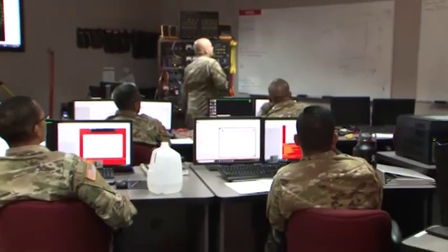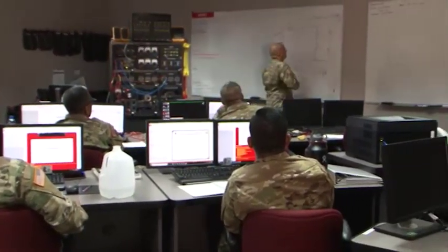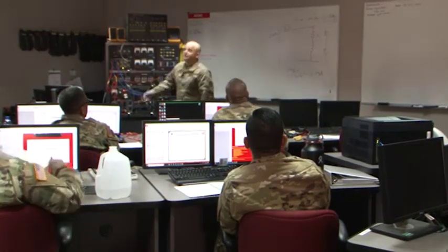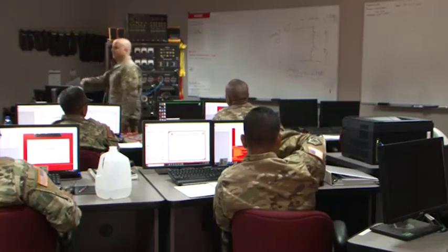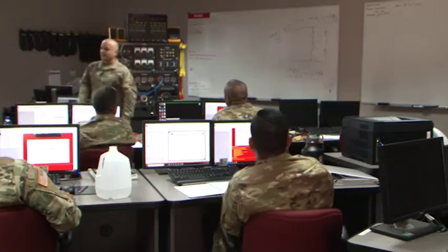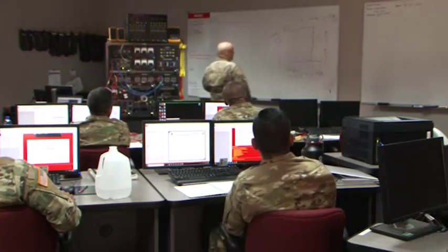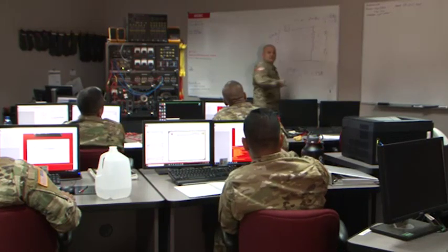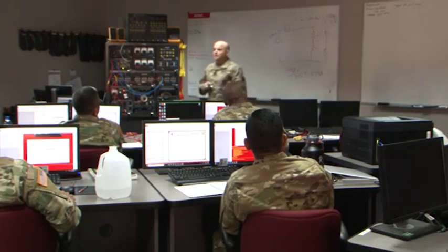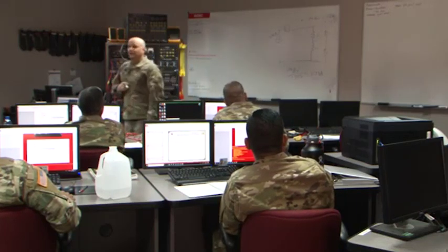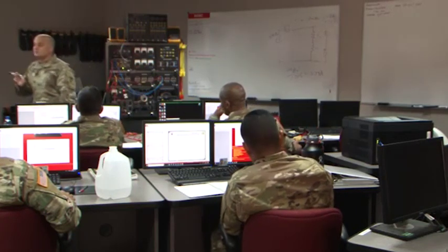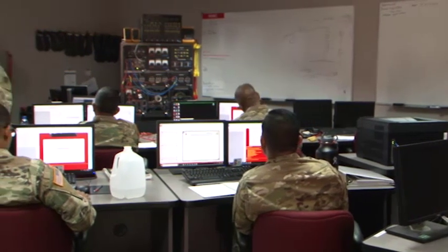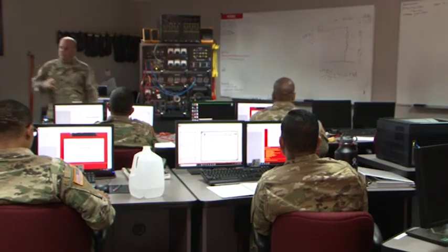Okay. All right. Well, we're going to call this an RL circuit. You hear RL circuit, RC circuit, RLC circuit. That just means whether it's resistive, inductive, capacitive, what things are all in that circuit, right? In this RL circuit, this is going to be out of phase with this, right? We don't just add those things up. One is going to be some value, and the other one is going to be an ohmic value, but it's going to be orthogonal to it, either positive or negative direction. And it's going to have a complex number associated with it. That's that little J, okay?